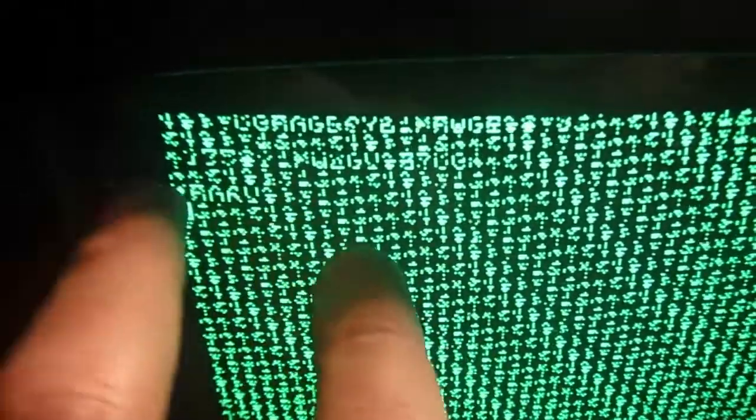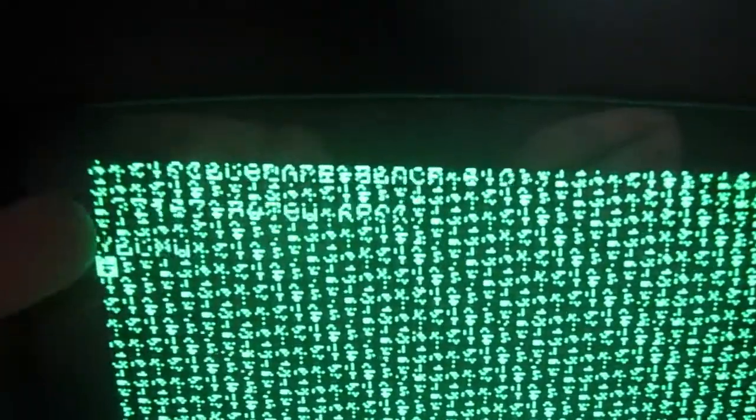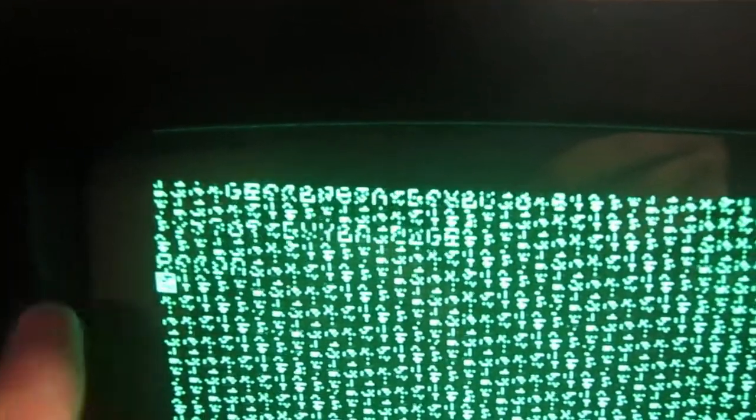It's quite a strange fault on the video circuit, but I can tell the BASIC started and there is a flashing cursor. I cannot understand what the bytes free amount is, but BASIC should restart.